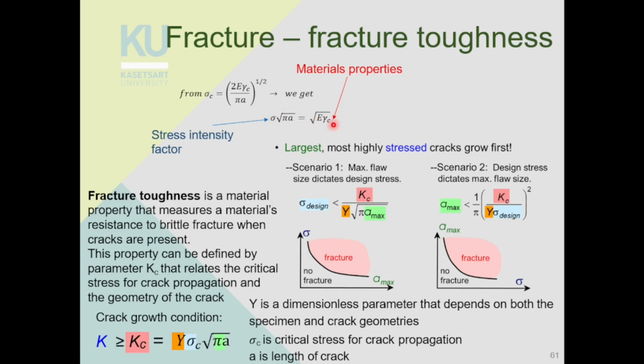So we make that equal. What that means is that the largest crack will grow first. The stress intensity factor tells you that. So if you have a higher a value, which is the length of the crack, it will grow first, right?